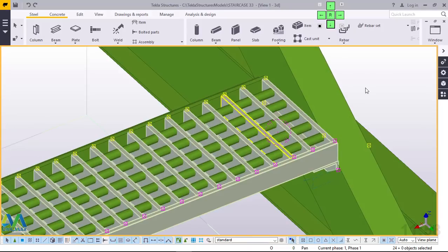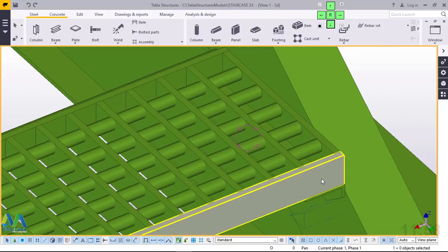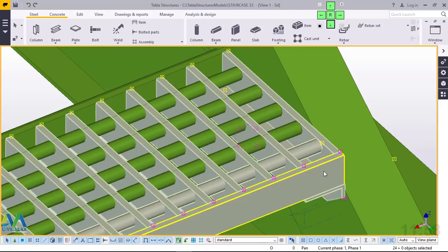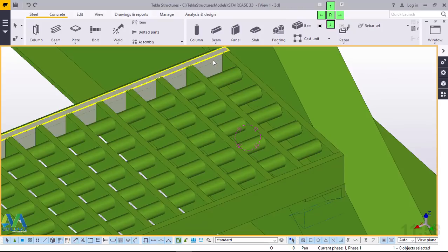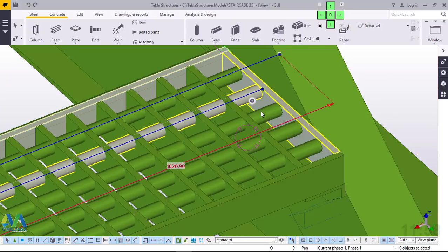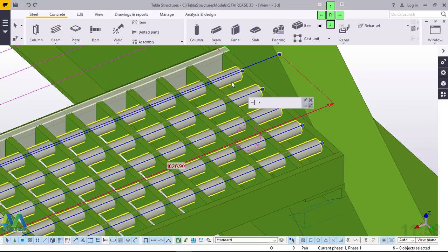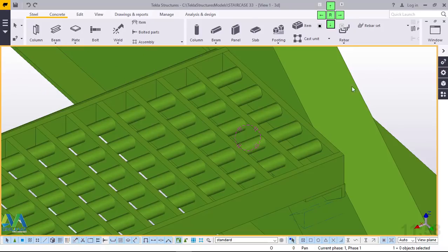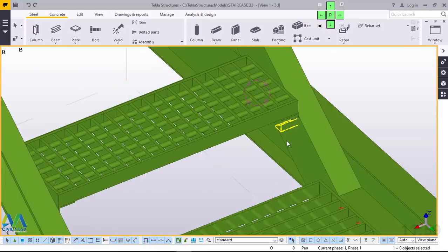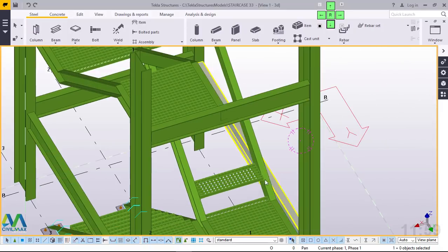Now I'll press Alt, but not everything is selected. I'll make sure I press Alt, and click on this, that, and this are included in the assembly, in this assembly. Perfect. That's been included. Even the support can be just to be welded on the stringer.